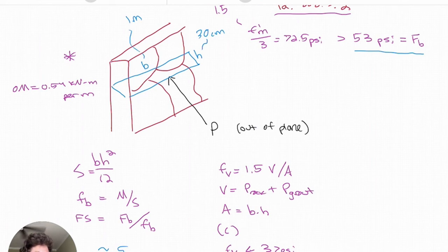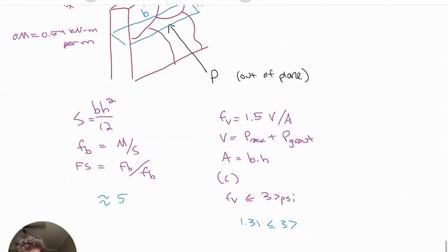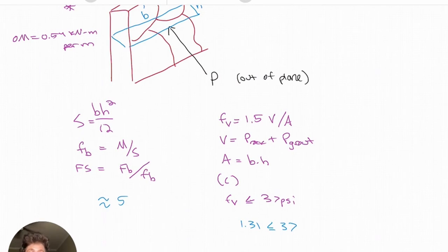And this is also pretty reasonable to actually raise the ramp fill so you can work on the ramp walls as they get higher. If you wish to fill the ramps greater than 1 meter per day, a site-specific calculation should be performed considering some of the other forces that are going to be occurring in this situation. And that will conclude our ramp wall stability checks that are really just a background for our general rule that we reported in the previous lecture.